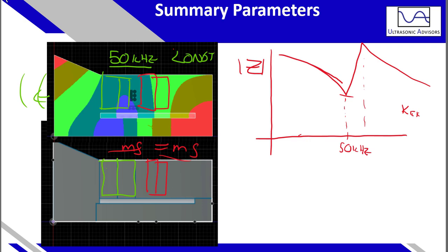So what happens is your piezo becomes less effective at driving. Therefore, your impedance increases because you have less displacement, less energy, and your coupling factor decreases as well. So when we go from A to B, your impedance increases. Your energy in your system will decrease.